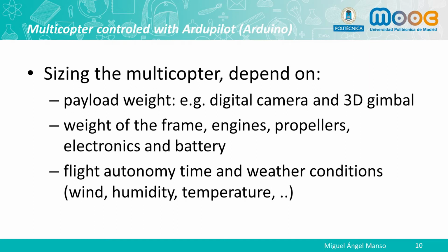Quadcopter controlled with ArduPilot. Sizing the multicopter depends on payload weight, for example digital camera and 3D gimbal, the weight of the frame, engines, propeller, electronics and battery, flight autonomy attained, and weather conditions: wind, humidity, temperature, etc.